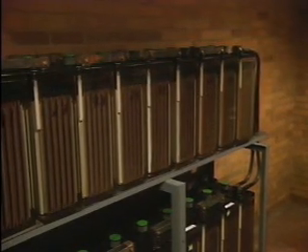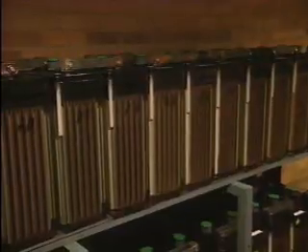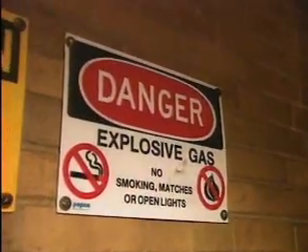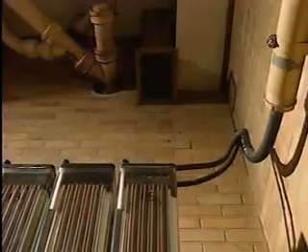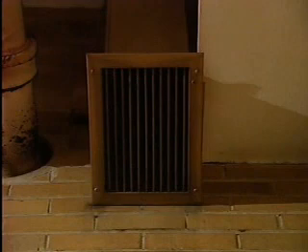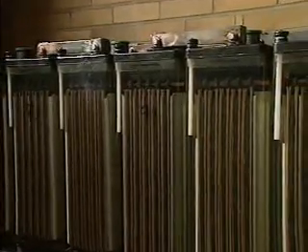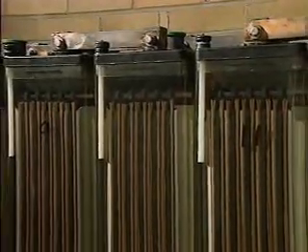Batteries also use chemicals that give off hydrogen gas as a byproduct. Hydrogen forms a hazardous mixture when it's combined with oxygen in the air. The slightest spark can cause an explosion. For this reason, smoking is not allowed in battery rooms. Proper ventilation is extremely important in battery areas. Vents reduce the chance of explosion by safely removing the hydrogen gas and also the acid vapors given off by batteries. The acid that batteries contain can burn human skin and many other materials.